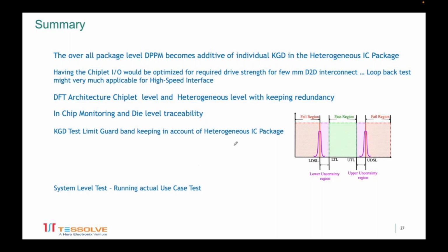How does this work for advanced packaging, where you may not be able to do some of this testing for known good die, certainly at speed? How do you see any issues with that? Yeah, so as I cited, the ATE will certainly have a limitation at a fully packaged level.